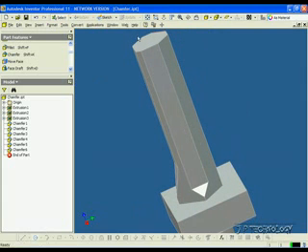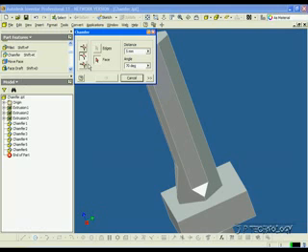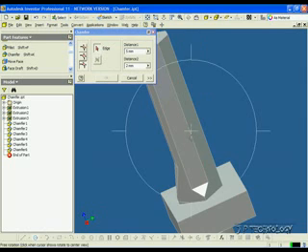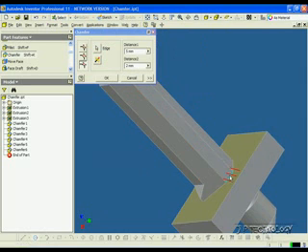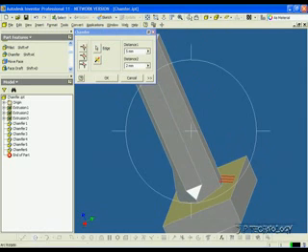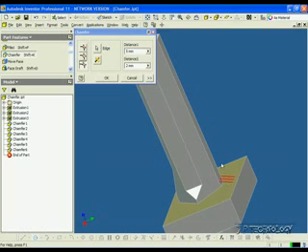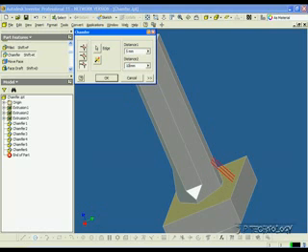Now, there's another one we can do too. Let's click chamfer, and we can use the distance. So let's click this, and what we have to do is click an edge. So let's go to the back here. Let's click this edge here. And right now there's two distances. So using these two distances, we're able to change the pitch and the run. So if we change this to 10, it's going to go up. If we put it to 1, it's going to go down.